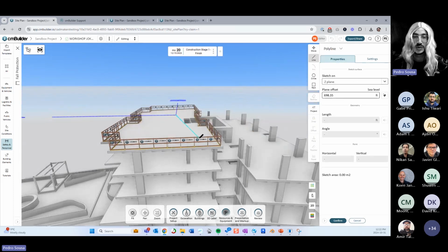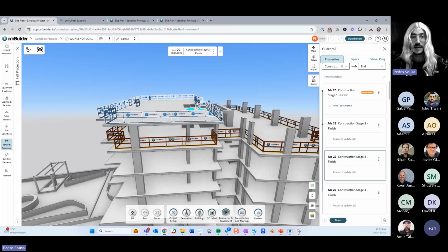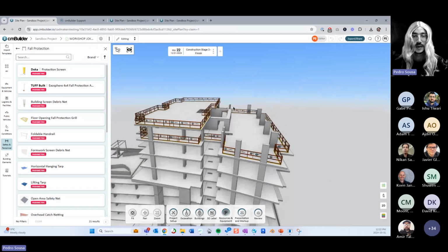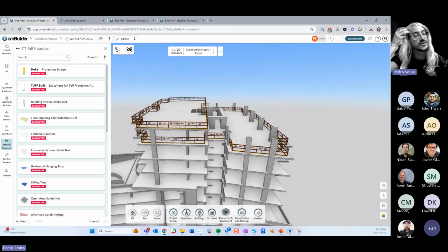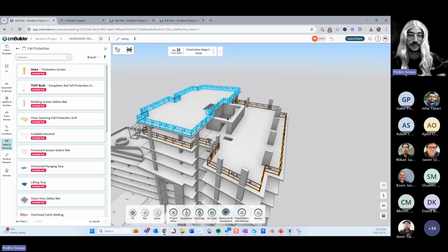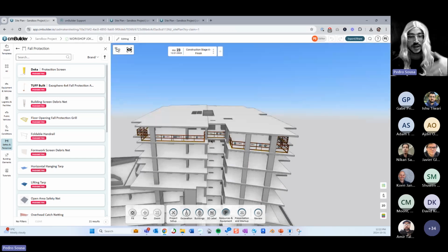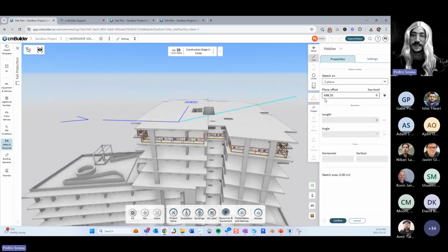And then I can use the projection of the previous one on the top one, right? So when I hit confirm, now this slab projection is supposed to show up at this milestone only. Okay, so that you can create the sequencing of safety measurements and so forth, using your pour breaks, using your projections. So a bunch of interesting things for you to create to work fast, right?